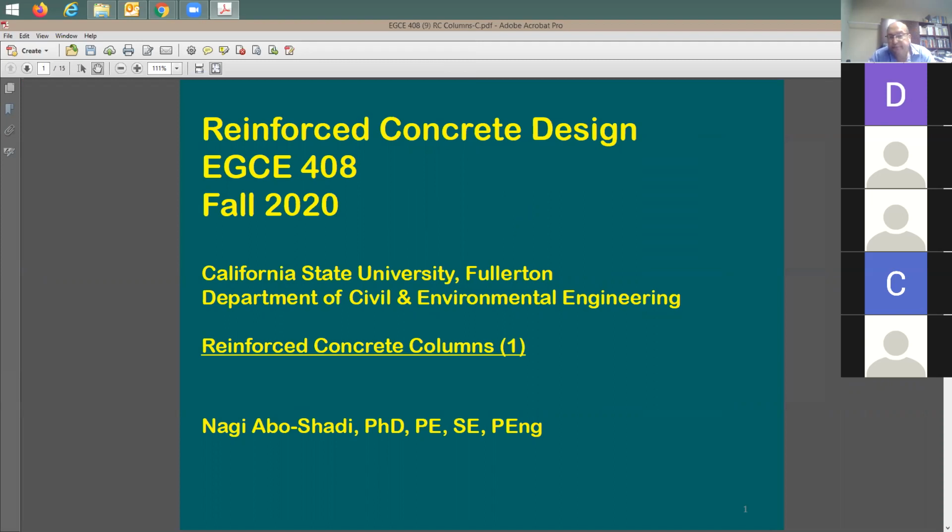Actually, a very initial assumption we do for designing is that we want a beam that's going to be in tension controlled area. This is correct. You'd like it to be in tension controlled area. So what are the factors before we design? We need to define just to get to the size of the beam we want in design. What are the factors? Yes. Factors can be the demand that you have in your beam, how much moment you want to support. Okay, that's how much shear, actually like the forces.